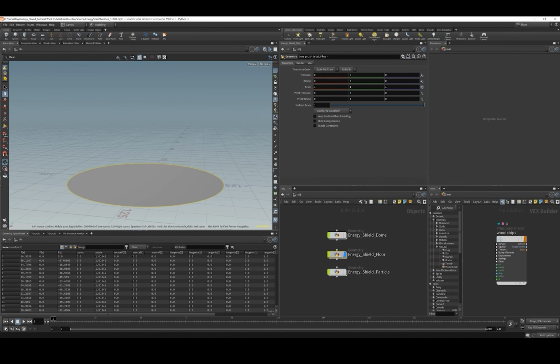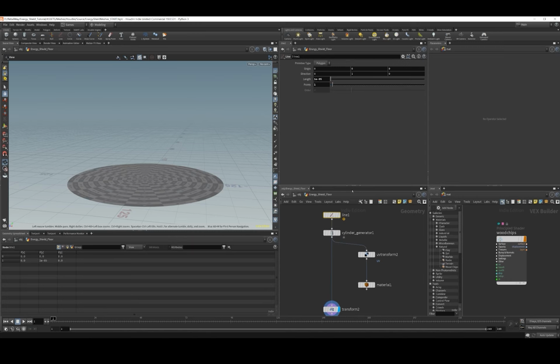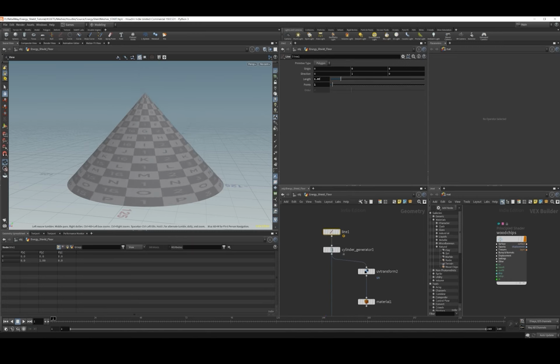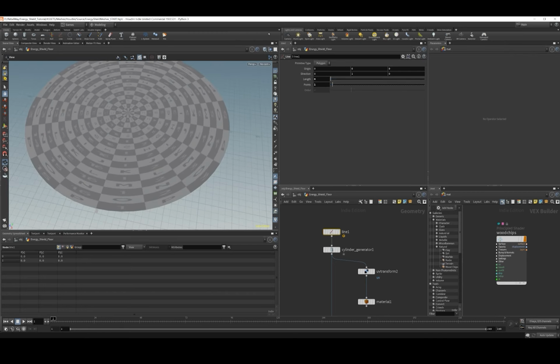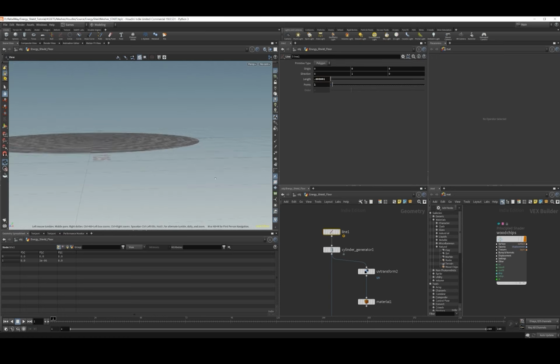All right, so let's move on to our floor mesh. This is going to be a lot simpler. We're simply going to start off with our line again. Now, this was up quite a bit for our cylinder, but I gave it a very low value because if you go all the way down to 0, it gets rid of your grid. You can see as I snap it. And so just for a sanity check, I don't think it really matters, but I just do a very low value. So you can see it, 5 zeros and a 1, and that keeps our grid there.